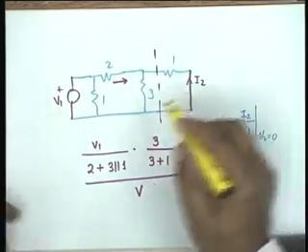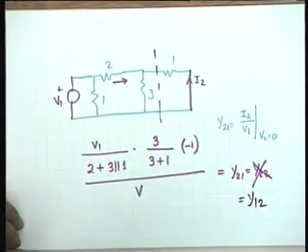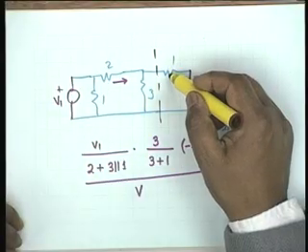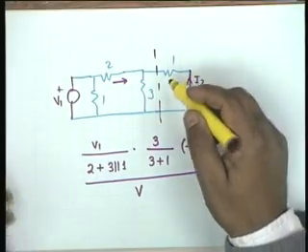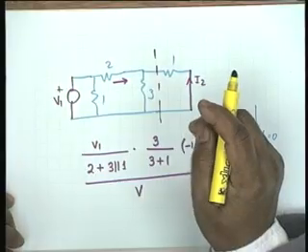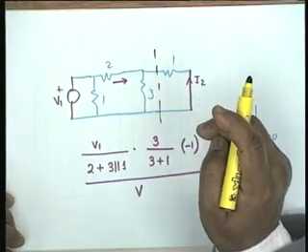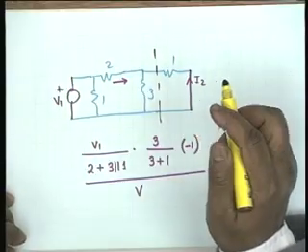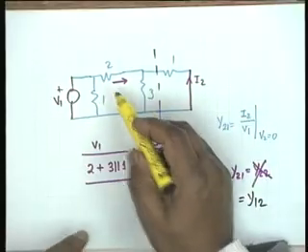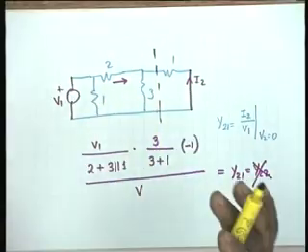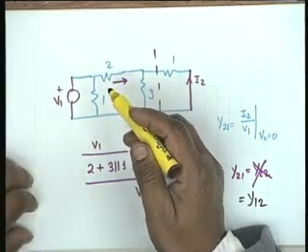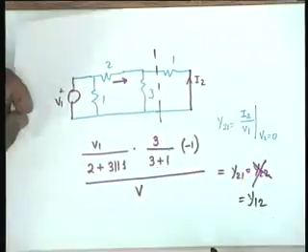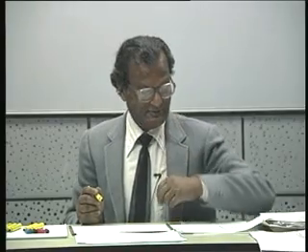What we could do is you could calculate the y parameters of this by inspection, but this resistance affects Z2 too. It does not affect any of the y parameters. So it is not a straightforward comparison with the equivalent circuit. You could also say this T 2, 3 and 1, that is a T equivalent, but this 1 affects y11, not Z11. Is that clear? So one cannot apply equivalent circuits here, but wherever applicable you can do that.